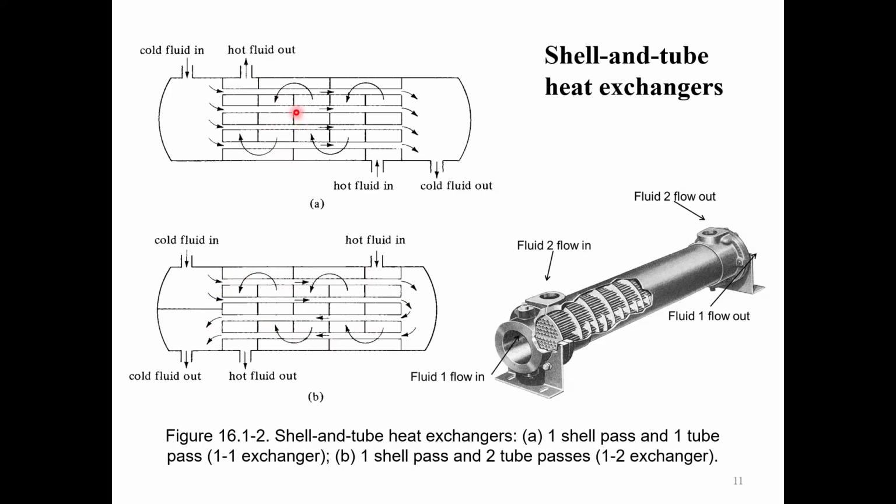They can also create turbulence within, and you know that when you have turbulence, your heat transfer coefficient will be high. So your heat transfer will be higher as well, and the design will be much more compact. So there are different purposes for having these baffles.